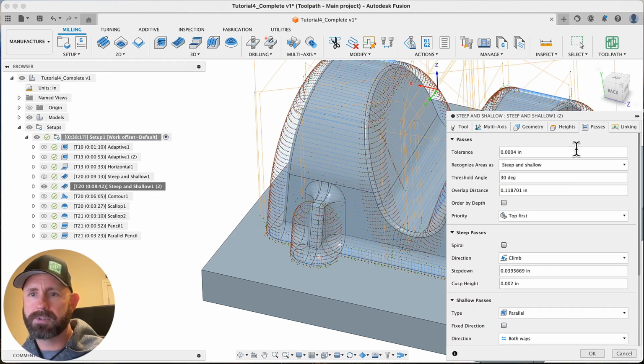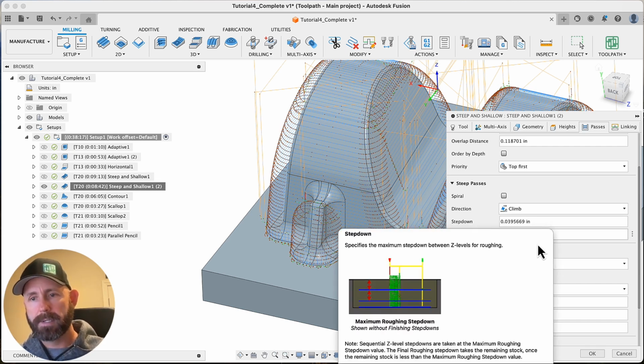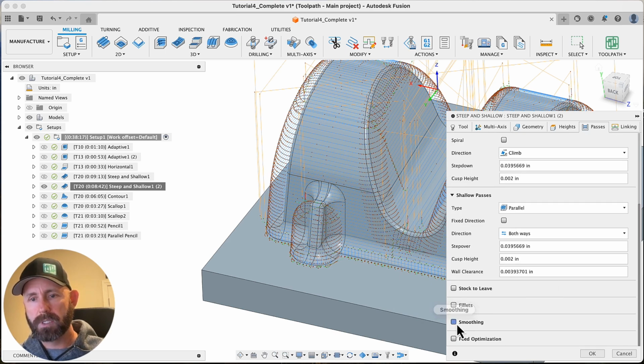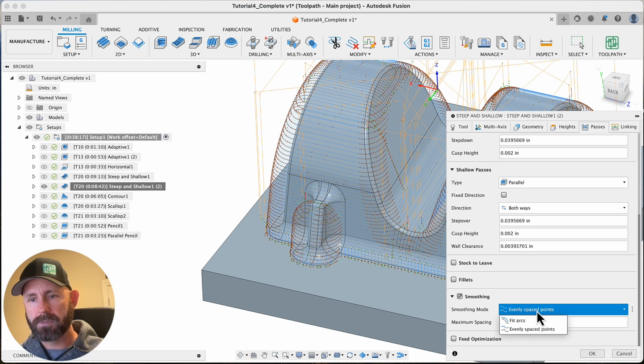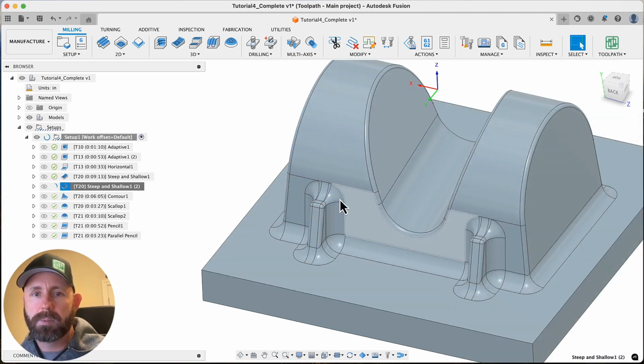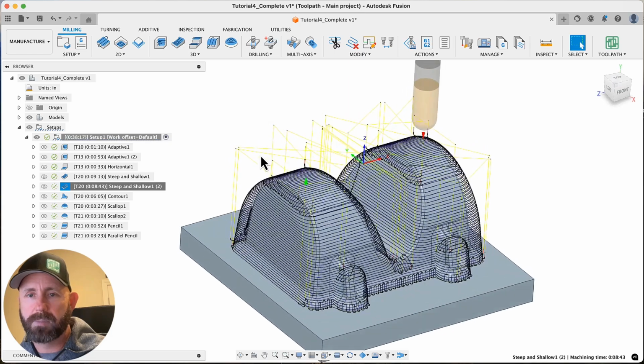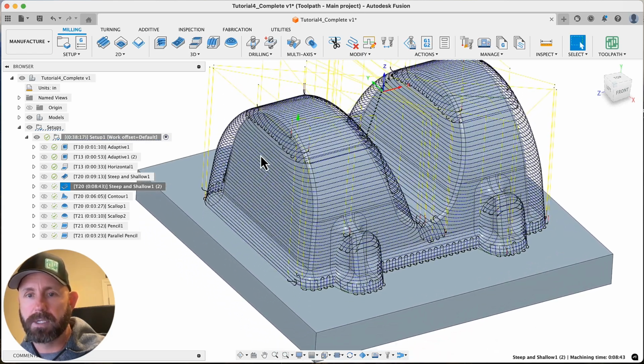The best surface finish I've ever seen off a Haas machine, and I'm not knocking Haas, is on my 2008 VF2SS with a zillion miles on it, leveraging this smoothing setting and even point distribution. A lot of people know about smoothing as arc fitting, but even point distribution is really good at giving a very even point distribution. My buddy Rob Lockwood said a long time ago in one of his videos, if you haven't watched them, they're all pretty old, but there's so much good stuff in there.